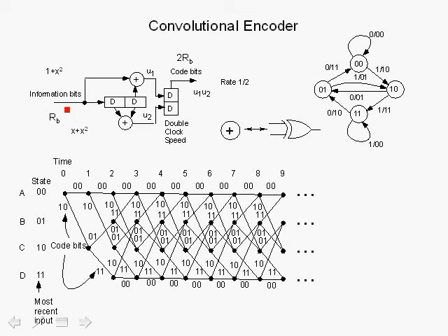So for example, if you collect a number of information bits and use a block code and add, for example, more redundant bits to it, it only depends on that collection of information bits, and it doesn't depend on the previous information bits. But in the case of a convolutional encoder, the output codes depend on the previous values of the information bits, and that's due to the operation of the linear sequential circuit here, the shift register with the operations as we've shown.